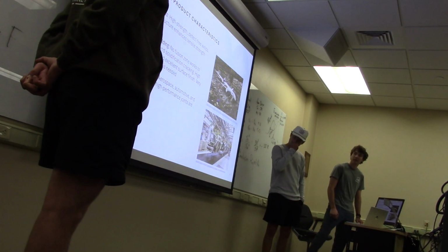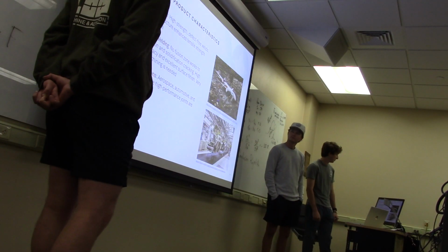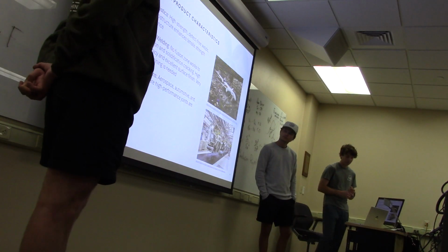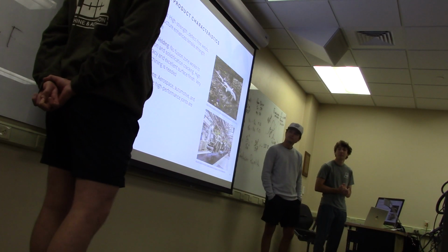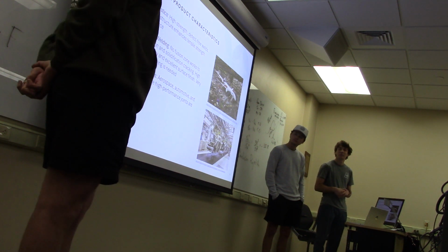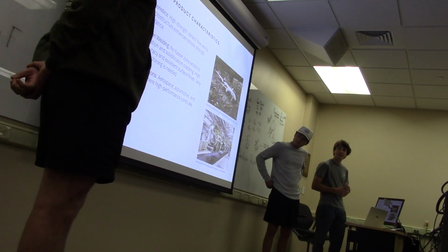And the output, the final product, is high-strength, defect-free welds with fine-grained microstructure, which enhances the tensile strength and fatigue resistance. There's no fusion zone, which works to eliminate segregation, solidification cracking, and gives high dimensional accuracy and excellent surface finish with very little post-weld machining needed.